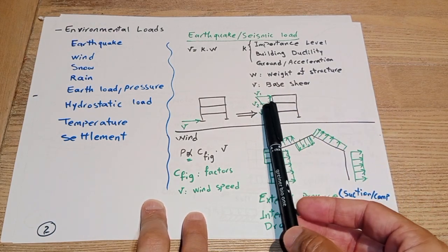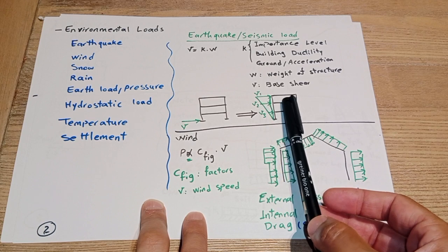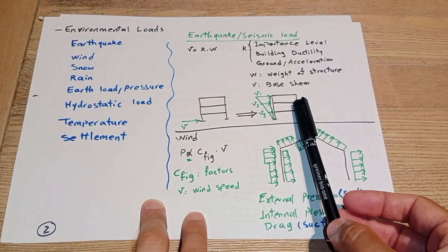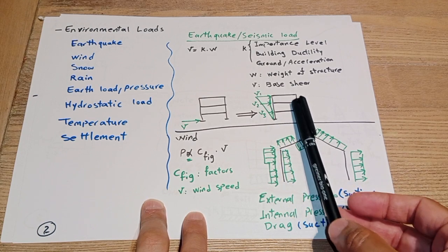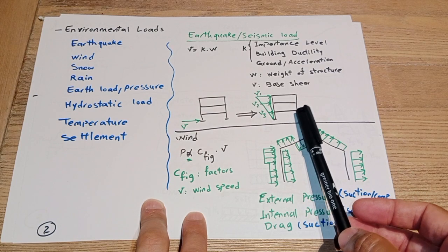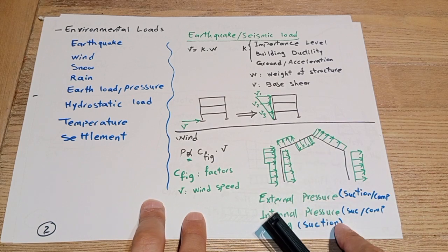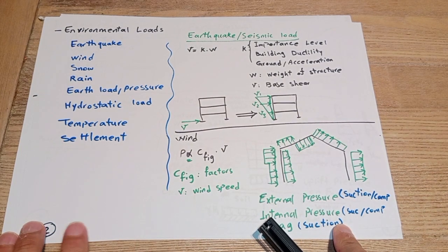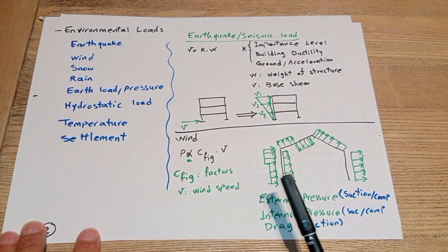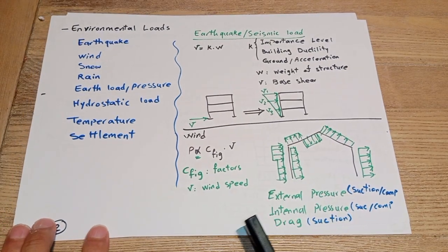It still depends on the mass of the stories, and in this case we assume that all the stories have the same mass value, but if we have more or less, we need to deal with the stiffness of the elevation levels and also the mass of the structure in each level.